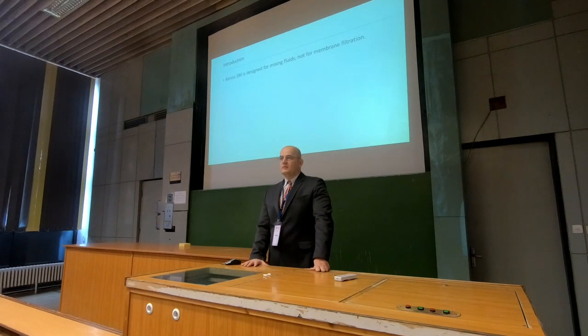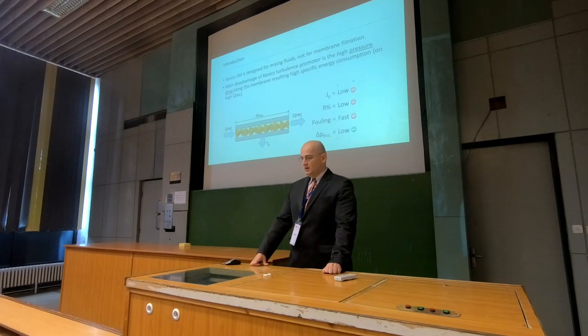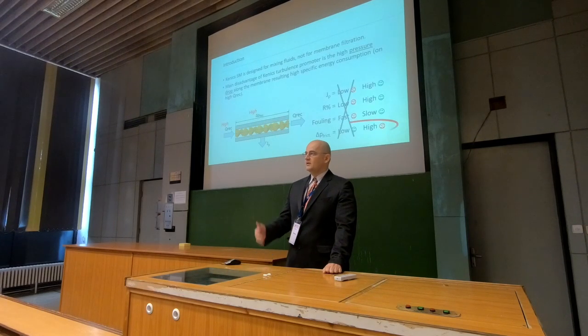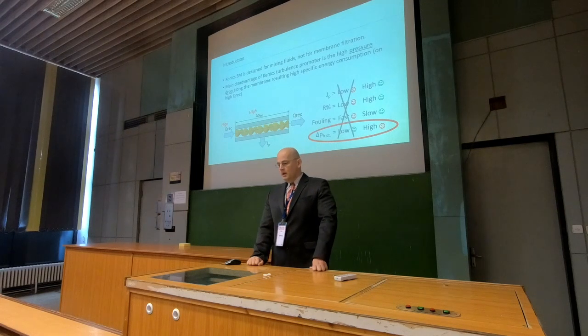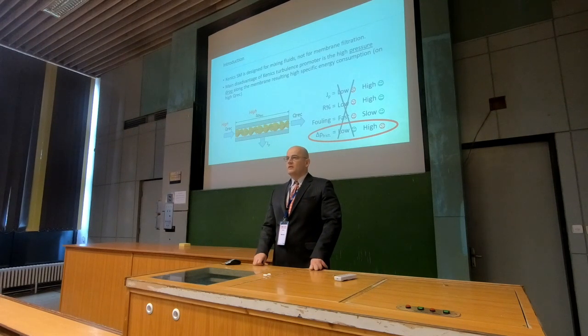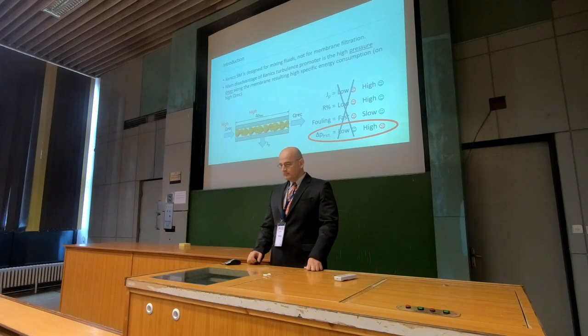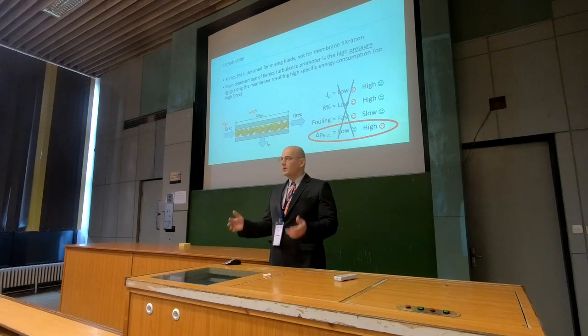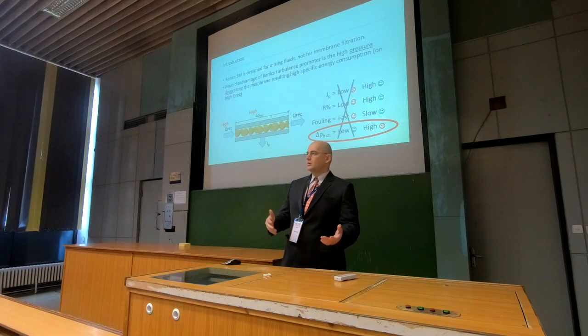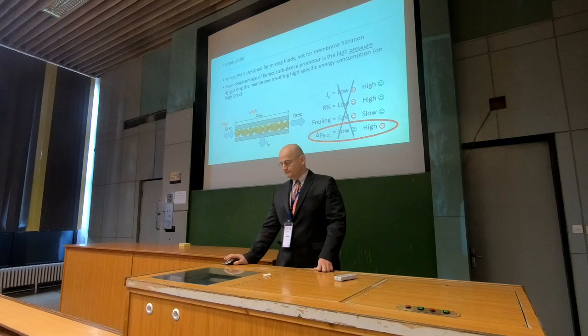The Kenix static mixer is designed for fluid mixing, not for membrane filtration. And it has a big disadvantage: if we put a Kenix static mixer inside the tubular membrane, at higher flow rates it will cause higher friction pressure drop along the membrane. So it can be used only at lower flow rates.